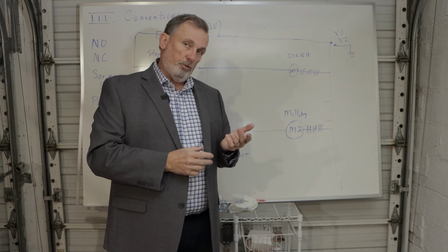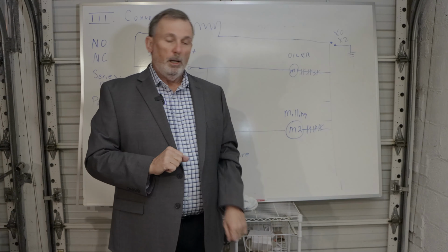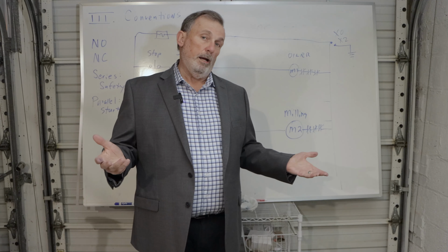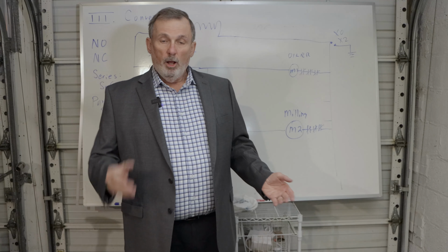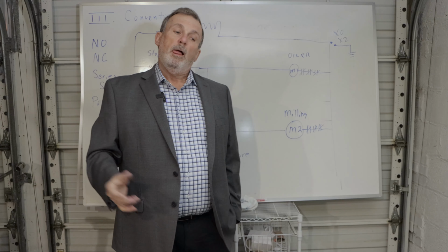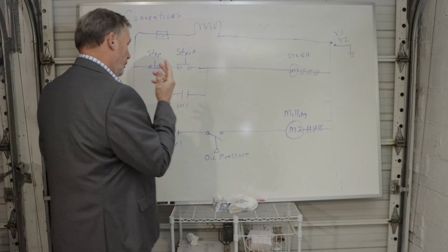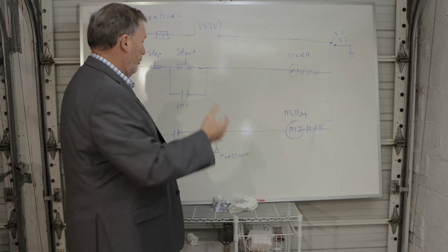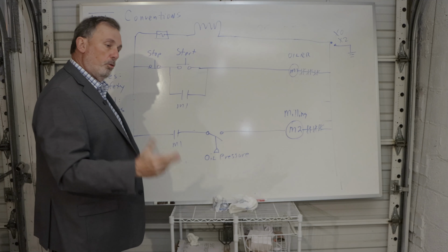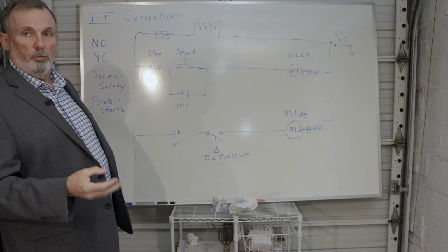I use thermostats and other sophisticated temperature controls to maintain that temperature. However, I don't want to heat the building warm and toasty on the weekend or at night when there's nobody in the building. So all of these parameters go into what we call a sequence of operation. And the sequence of operation ultimately will be represented in a series of ladder diagrams. So this is how we take a graphic representation and turn it into what we want to have happen when we run machines, systems, and so forth.